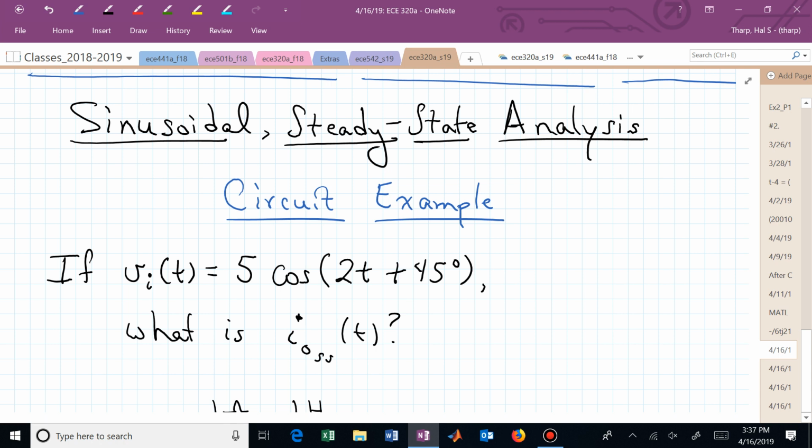But you have had some homework problems that talk about break frequencies and finding that frequency. And that's sort of Bode plots and filter design that we'll be using after exam number 3. So I'm not sure I answered your question, but be ready for designing a low-pass filter. You should be able to do that based on all the discussions that we've had this semester. If you get into an interview, you better be able to design a low-pass filter, or at least draw a low-pass filter and find the break frequency or the pole where that roll-off begins.